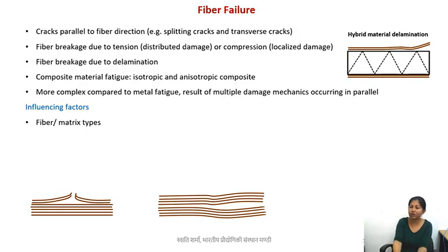In fact, one of the issues with carbon fibers is that the surface of carbon fibers can be very inert, and you may have to do certain chemical treatment of the surface in order to make it more compatible with the resin, with the matrix. So this fiber-matrix compatibility also determines your fiber distribution. However, the design of the composite can also determine the fiber distribution.